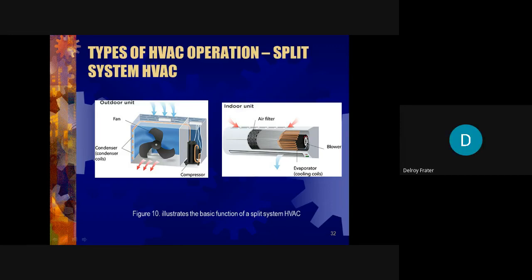If it was doing that as the regular type, then we'd be at square one, where we have to start the compressor when it shuts down, and we'd have the regular starting current, which is always 6 times or more the running current.